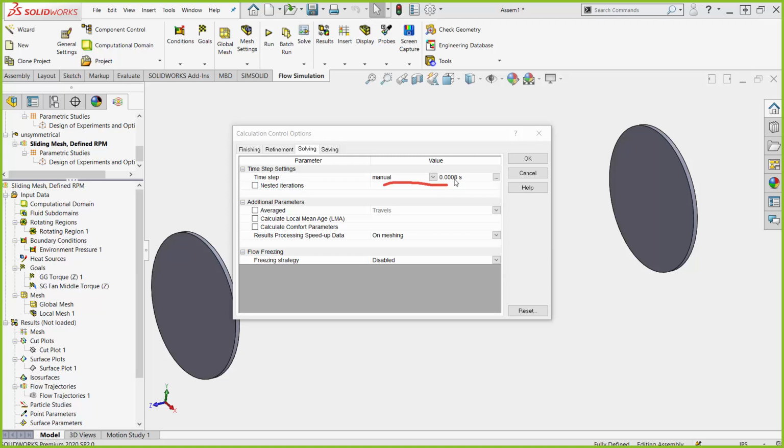So I'm losing access to some perturbations that are happening. I'm losing accuracy. So everything with a grain of salt, all right? We're doing this for early design iterations to quickly get to answers so we can get an idea of our results. Final answers, please go back to auto and let that be accurate.